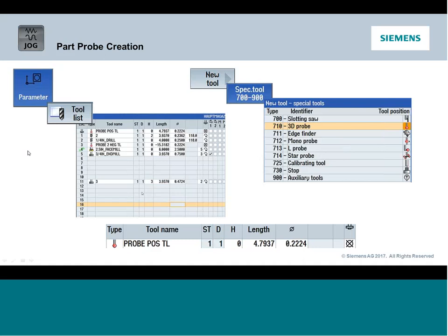The only time we get into a case where we have trouble with our standard cycle supporting it is lasers. So lasers is a different beast. When you get to lasers, and that's for tool presetting, there's all sorts of different types of focal points, types of laser designs. So the cycles that run those lasers are very specialized. So then you are going to need to use the manufacturer's cycle for laser.